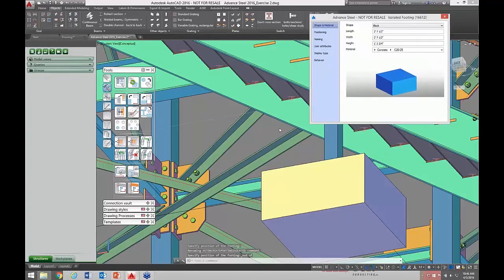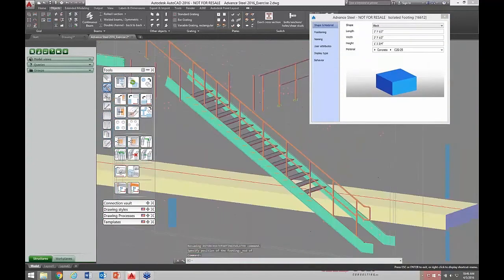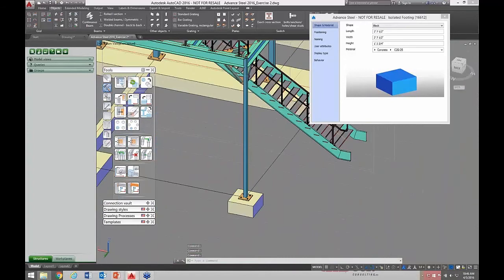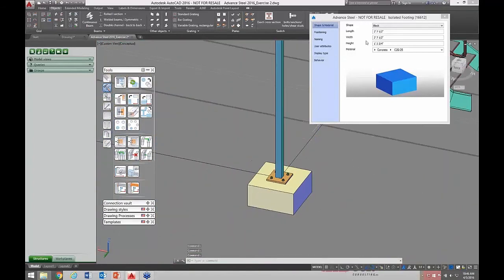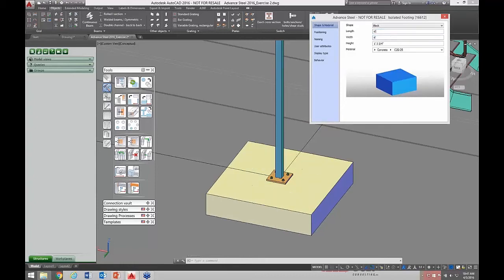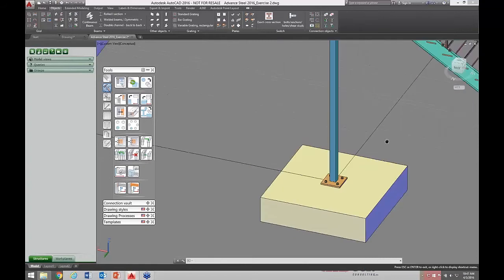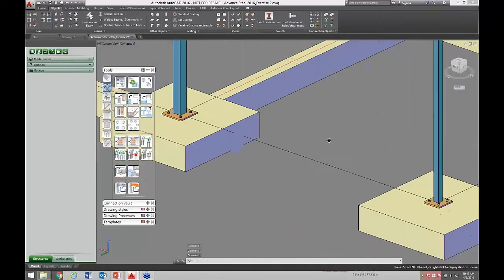And then I could make changes as far as size goes, in the same fashion as the other macro dialogues we've been bringing out. Maybe this is a 6 by 6 and 1.5 feet thick. Okay, we can change our concrete value, material being used.